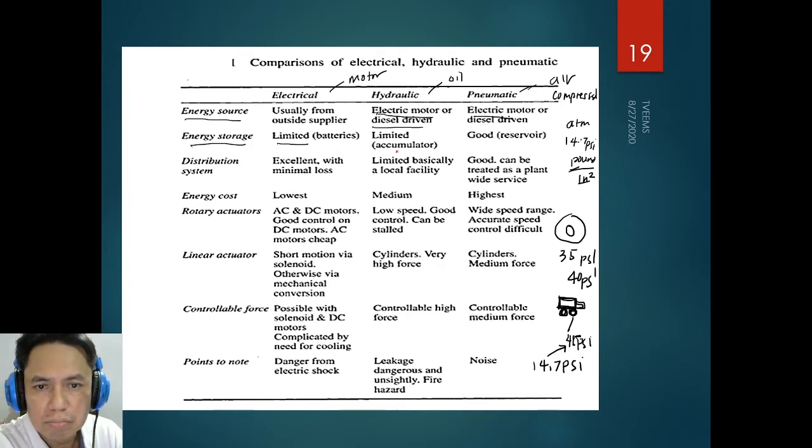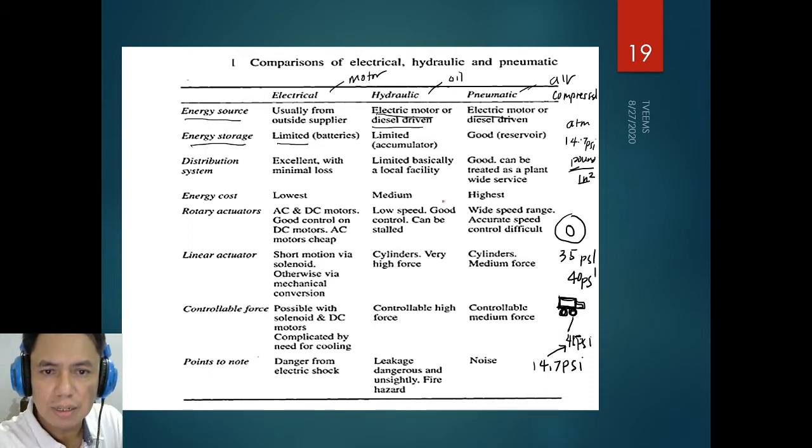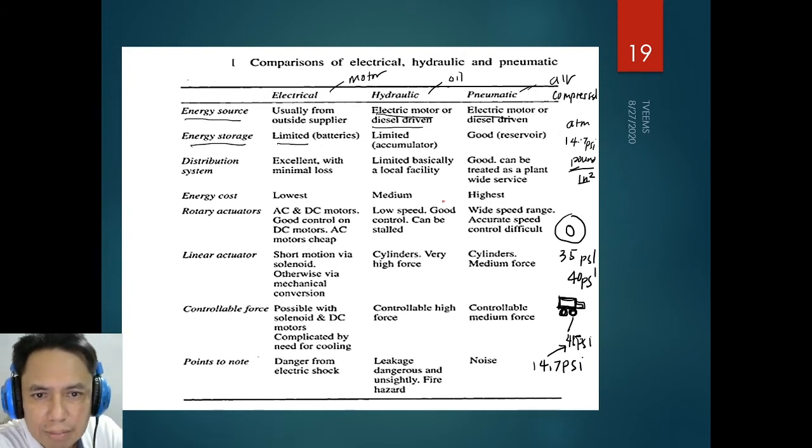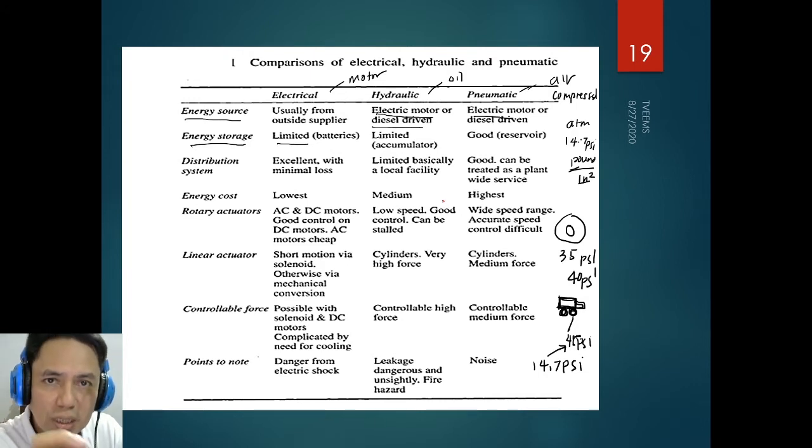When you are operating the hydraulics, it is powered by this fluid, and then the pressure goes up, and the bladder, some kind of rubber casing, is being pushed up. But once the power is lost, that stored energy will be the one to provide the necessary power for the system to continue.